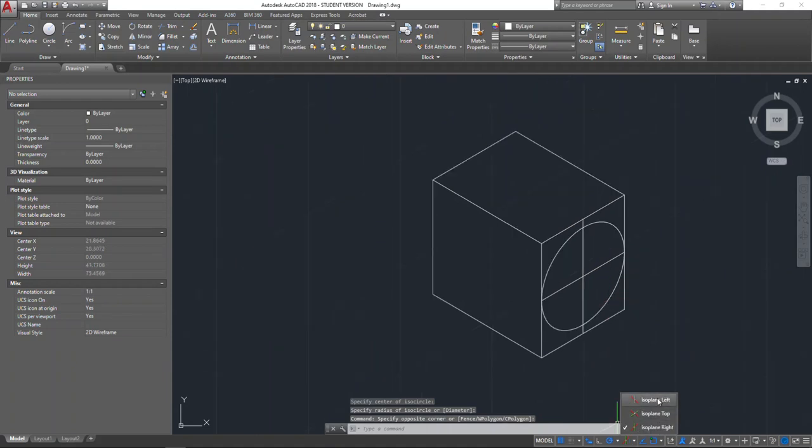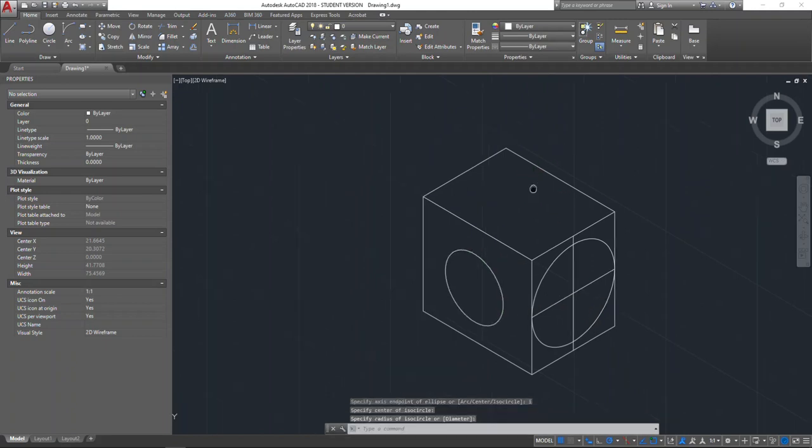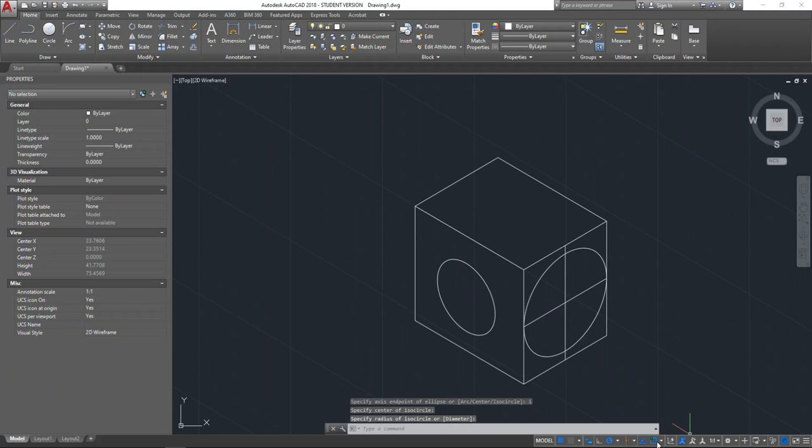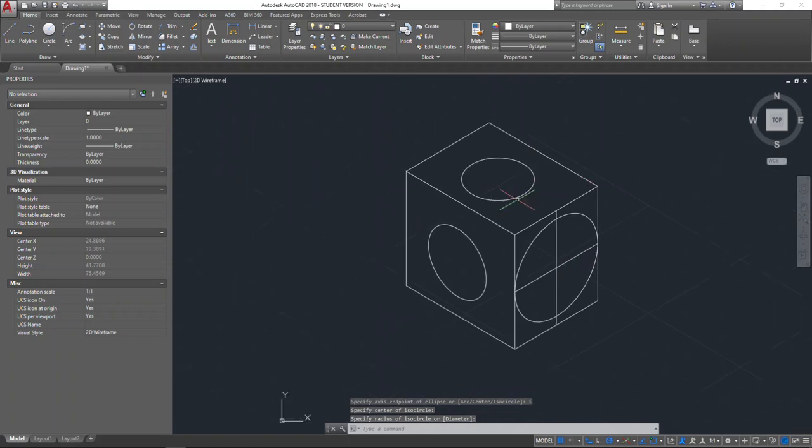If you wanted to go into your left view, we can type ellipse again, then type I, and you would be in that plane. The same thing goes for the top. You would click down on this, go to isoplane top, then go to ellipse, type I, and you would be drawing a circle in that plane. So isometric people, fairly easy.